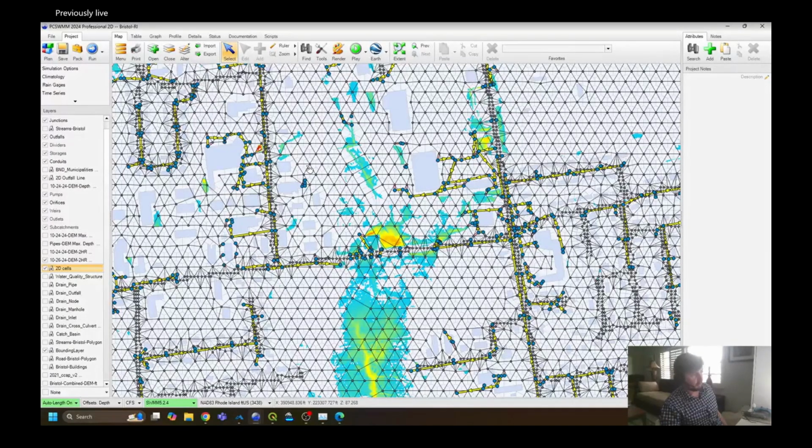There are a lot of interesting questions about how to deal with the flow length. Am I double counting flow length if I have the flow length of the subcatchment and then the overland flow of the 2D network? How am I dealing with the infiltration going on in the subcatchment and then also the infiltration going on across the 2D mesh? I think there's a warranted question for a little bit of research to test out which modeling approach is going to work better.